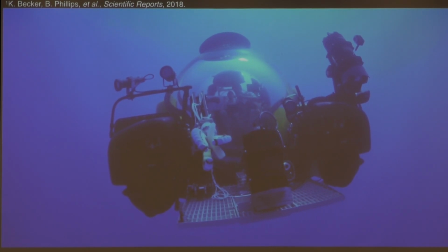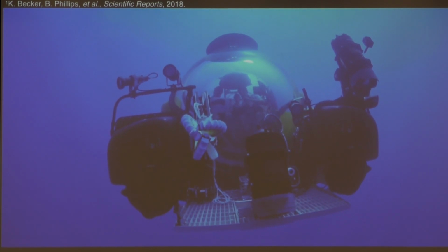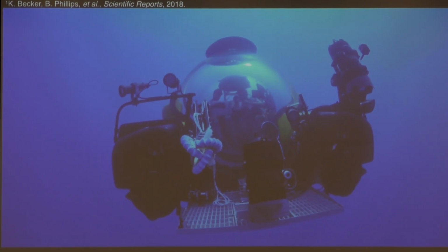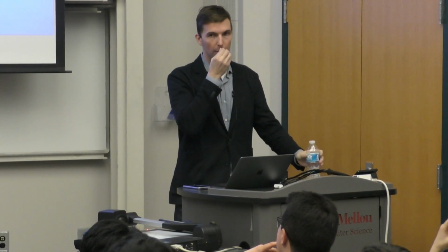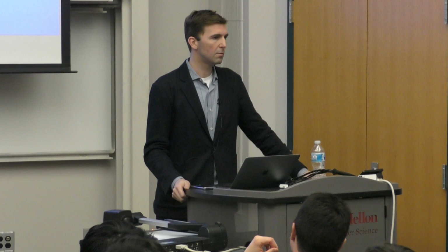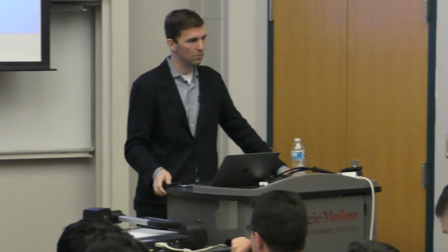You're under very large pressures, and water is roughly incompressible. I question whether those things are really soft rather than kinematically appropriate for the task. Soft or kinematically appropriate for the task? Well, it bends in a nice little circle around the squishy thing. Yep. But I bet if a human diver went up and poked at it with his finger, he'd say, "Oh, that's not soft." The actual organisms, you mean? No, the fingers. The elastomer filled with high pressure water, unless it really has an open exhaust valve to the outside, it's going to be very stiff.